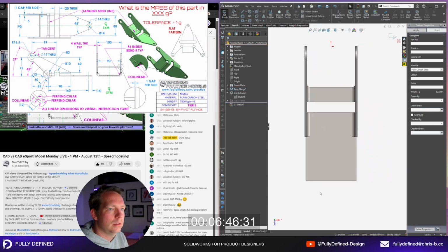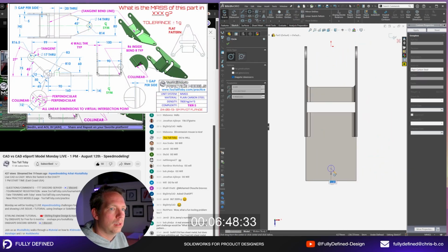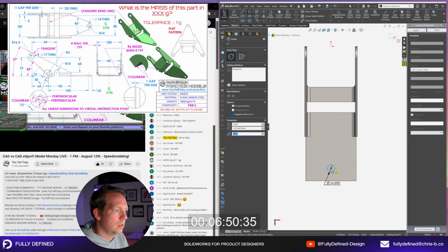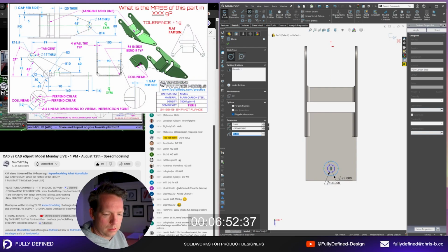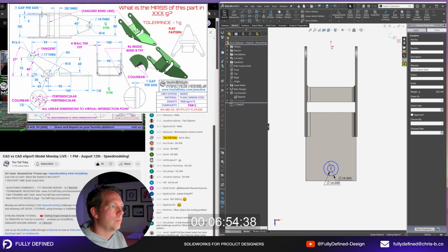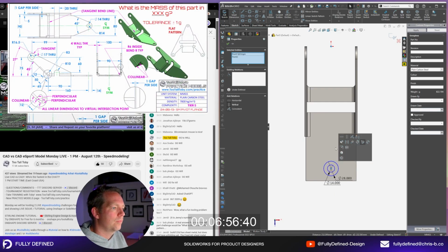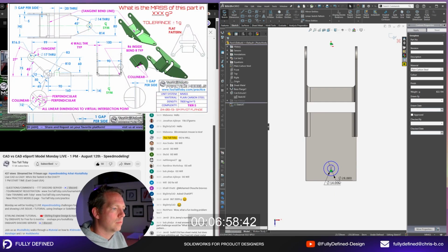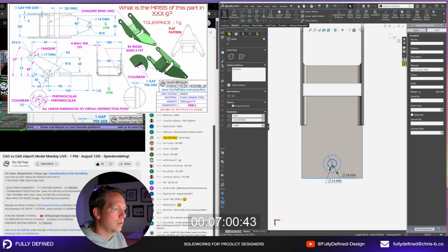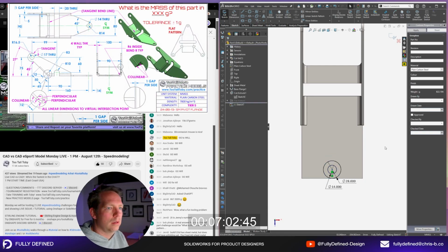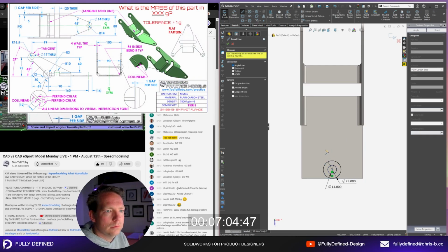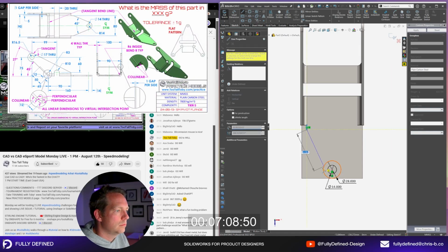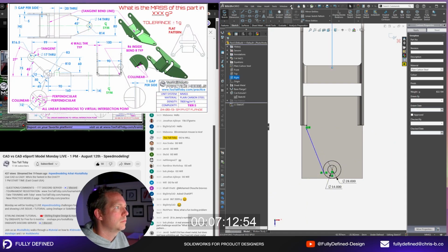That corner where it's coming down, even that could solve differently from one CAD system to another. So to try to keep it really CAD agnostic, I have to do things we might not do in the manufacturing world. Things like this relief here, it's so exaggerated. You probably wouldn't need that much relief, and it's just going to make welding more difficult. So, we do things differently in the real world, but when we've got people using all different CAD systems, we want to try to keep it fair for everybody.